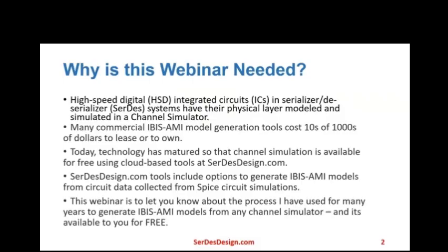Why is this webinar needed? High-speed digital integrated circuits and serializer deserializer systems have their physical layer modeled and simulated in a channel simulator. Channel simulators are designed to use IBIS-AMI models that are based on the IBIS specification. Many commercial IBIS-AMI model generation tools cost tens of thousands of dollars to lease or to own. Today, the SerDes channel simulation technology has matured so that it is available for free using cloud-based tools at SerDesDesign.com.